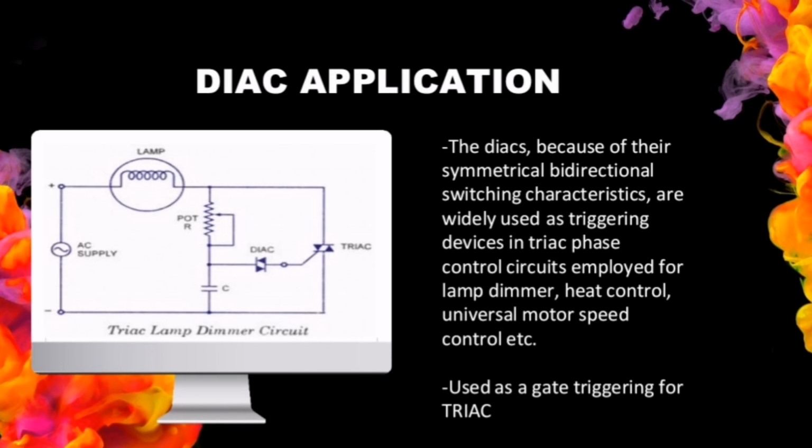One of the major uses of diacs is within triac circuits. Triacs do not fire symmetrically as a result of slight differences between the two halves of the device. The non-symmetrical firing and resulting waveforms give rise to the generation of unwanted harmonics. The less symmetrical the waveform, the greater the level of harmonic generation. To resolve the issue resulting from the non-symmetrical operation, a diac is often placed in series with the gate. This device helps make the switching more even in both halves of the cycle.